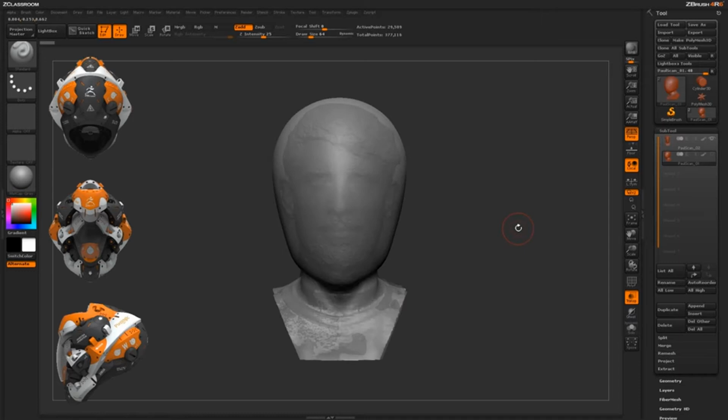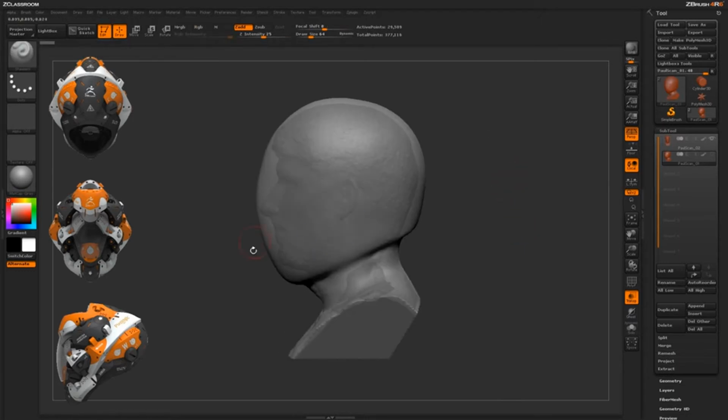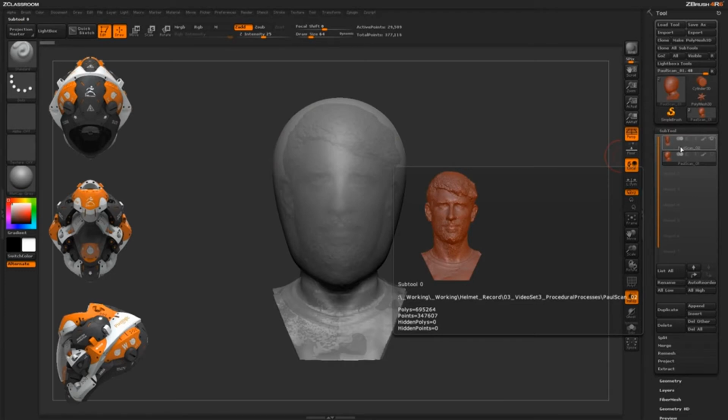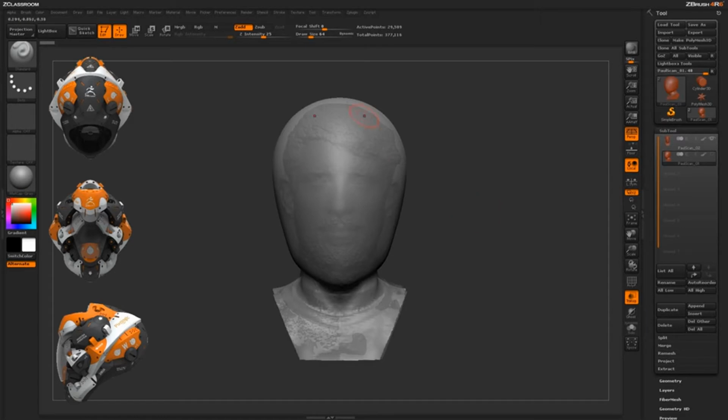Another thing to take notice of is the amount of empty space I've left around Paul's scan data here. This is to err on the side of caution. If you look at my scan data, it was pretty rough, so I'm not getting 100% accuracy off of that scan data. When this gets turned into a tangible element, I want to make sure I have enough clearance around Paul's scan data so it fits.